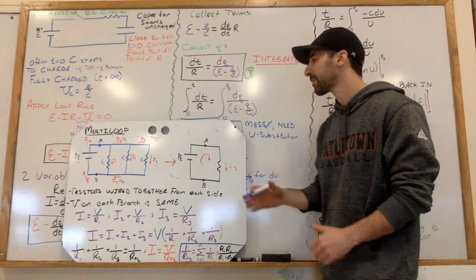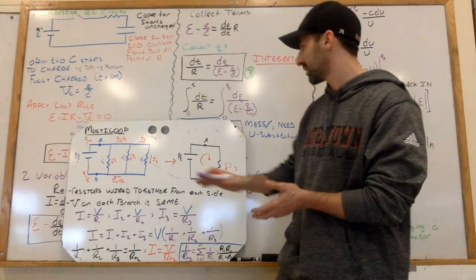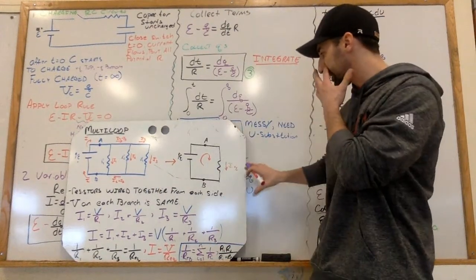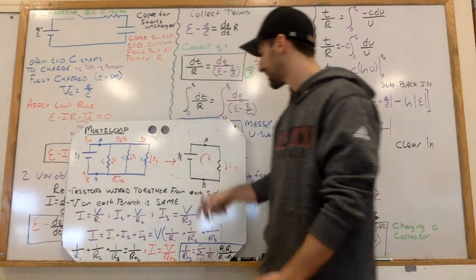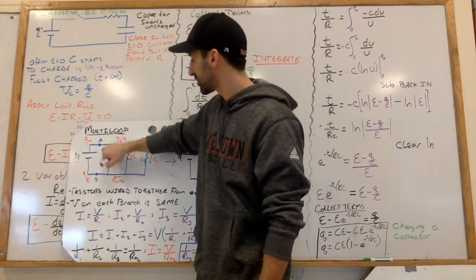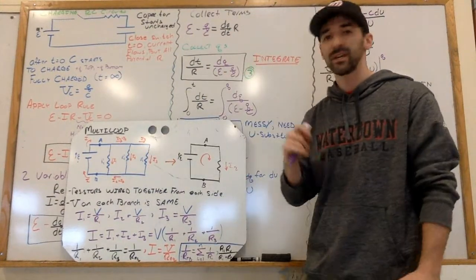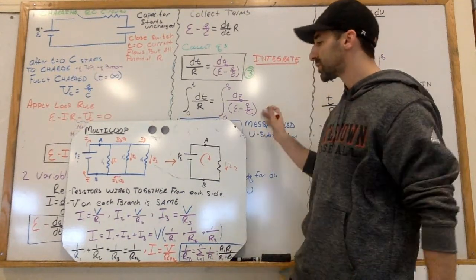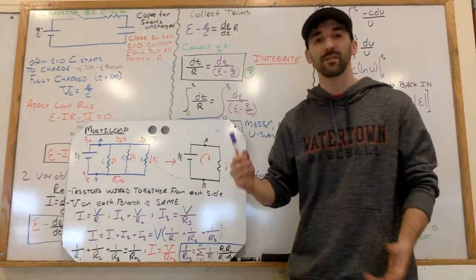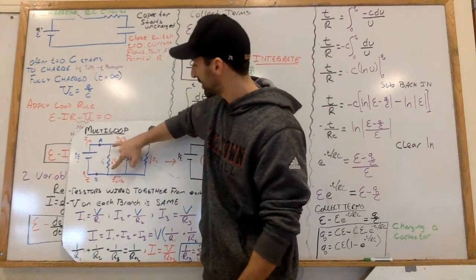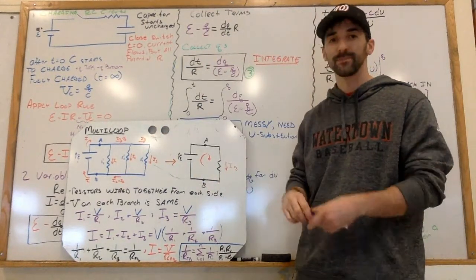Very simple math. Now, just like we did with a series circuit, we can do the same thing for a parallel circuit, where I combine everything to have an equivalent resistance. A parallel circuit is when we have resistors wired together from each side. In other words, I have potential at A and B wired across that resistor and that resistor. So our rules are a little bit different. We should be able to see that the voltage on each branch is the same because of the way it's wired. Again, our potential is wired essentially directly to either end of our resistors or our circuit element.